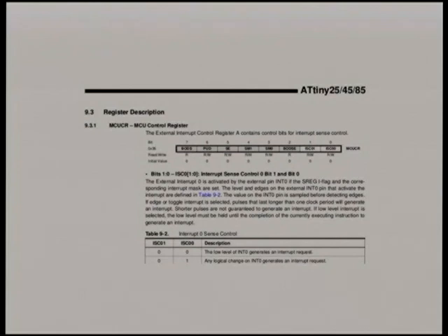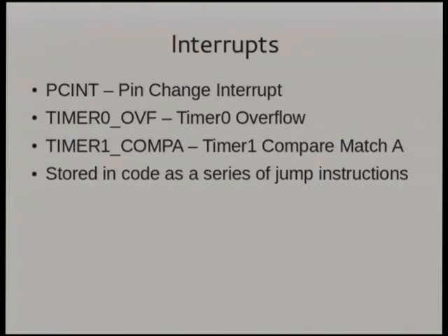So you can read through it, and here are some examples of interrupt names that you might find on an ATtiny85. PCINT, pin change interrupt, TIMER0_OVF, so timer 0 overflow. There are multiple timers on these chips, and they've all got numbers the same way that the ports all have names. I'll get to the timer things a bit later.